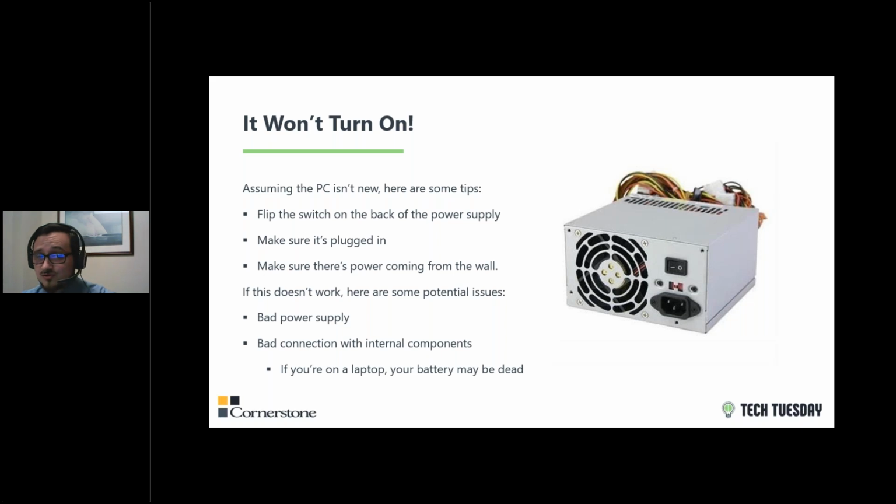The first problem is it won't turn on. We already covered some of these things, but assuming you've checked all the plugs, you know everything's plugged in, then you might have trouble if you try to turn it on and everything's black. The first thing to check is a switch, actually, after that. And I'm going to highlight real quick where that switch is on this mock power supply, right over here. I've highlighted it in yellow, and I'm also going to circle it with my pen right over here.